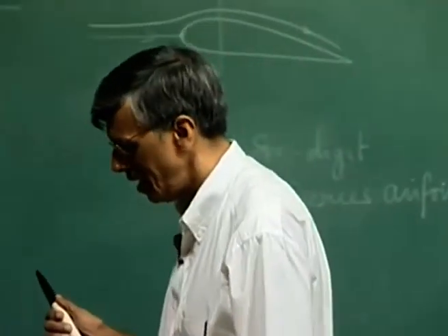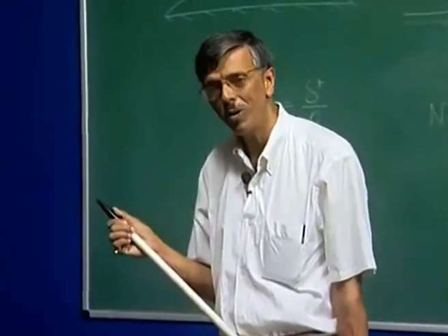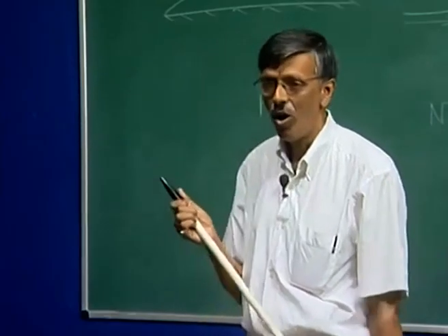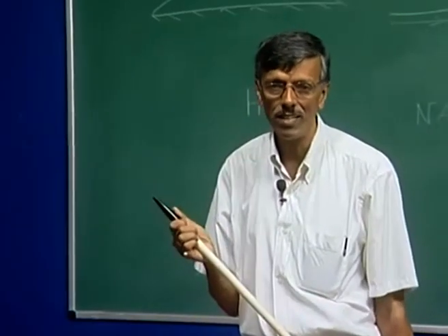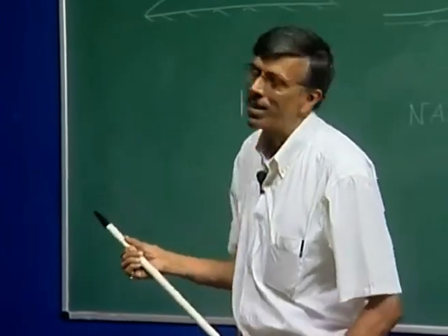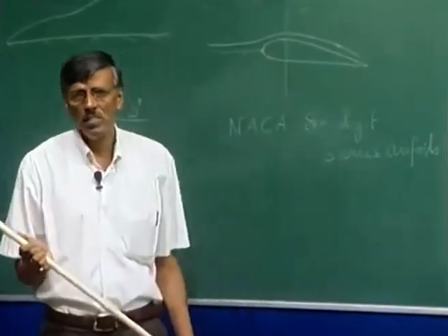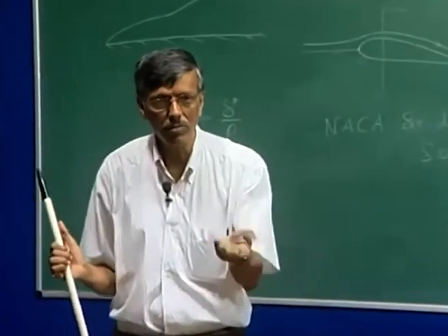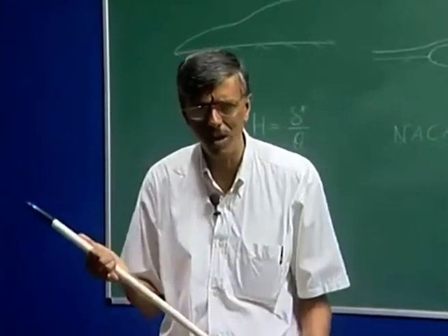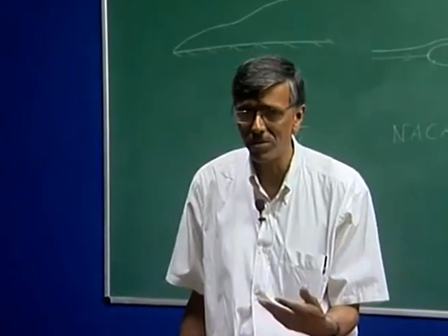However, those experiments by Schubauer and Skramstad specifically reported that they could validate the linear theory only when they created a disturbance inside the shear layer. But suppose you are flying an aircraft, of course, the wing surface vibrates because of structural vibration that can create a seed of disturbances from inside.